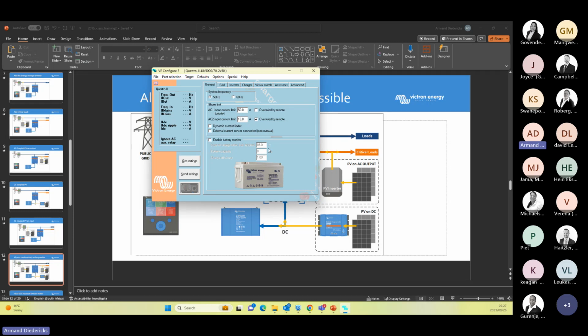Right, so on this side, on the left-hand side, you'll see the frequency out, the inverter voltage and inverter amps, then frequency in, voltage in, mains in, and then your VDC, which is your voltage on your DC bus on your battery. Your VDC ripple, that's the voltage that displays the ripple.